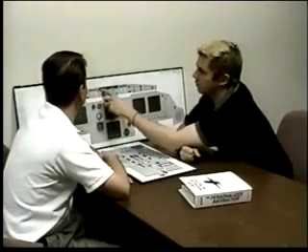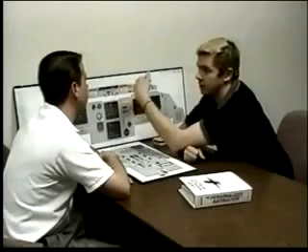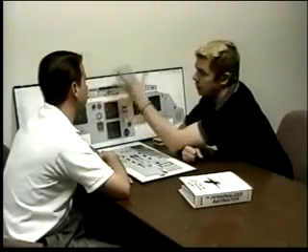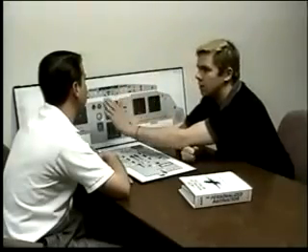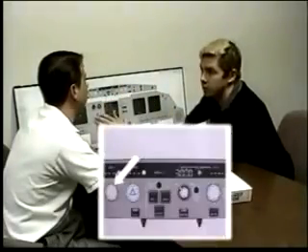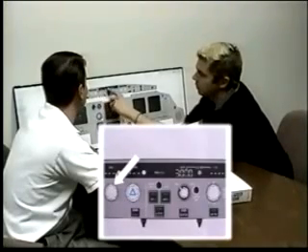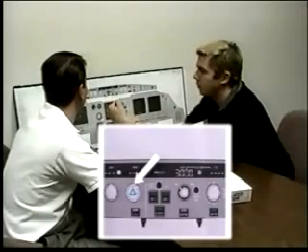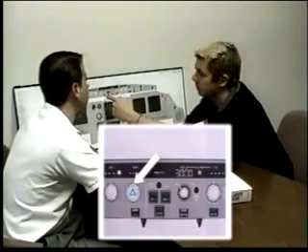It has no relationship to, like, the Boeings have this VNAV and the econ speed. There's no relationship of managed speed to the VNAV portion. We can get managed speed in any vertical mode or no vertical mode whatsoever. So pushing is a managed speed, pulling is a selected speed. With the lateral portion of it, pulling is giving me a heading or a track if I'm in track flight path angle. Pushing it is asking for LNAV.